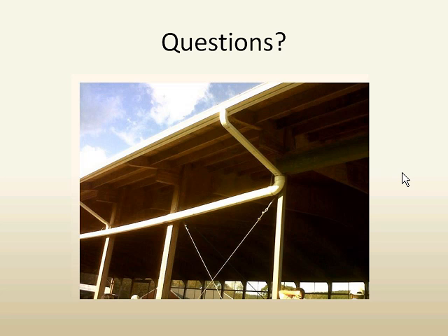We have a graphic that I'm going to show later on that talks about lowering gutters to avoid snow, and that's the only thing that I've seen in the literature on that particular question. But I think what Mike is trying to get to is you want to make sure that the gutter is wide enough to capture that runoff, especially if your gutter is down a little bit. You don't want the water to overshoot the gutter.